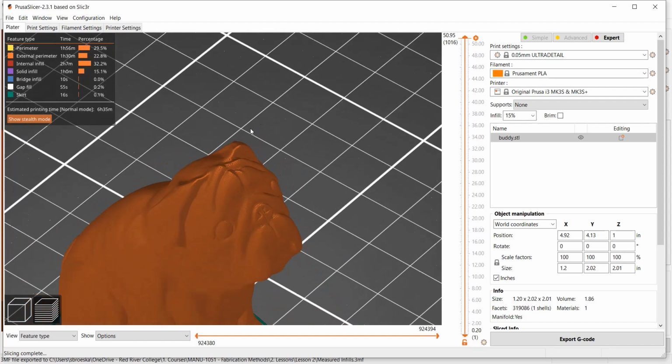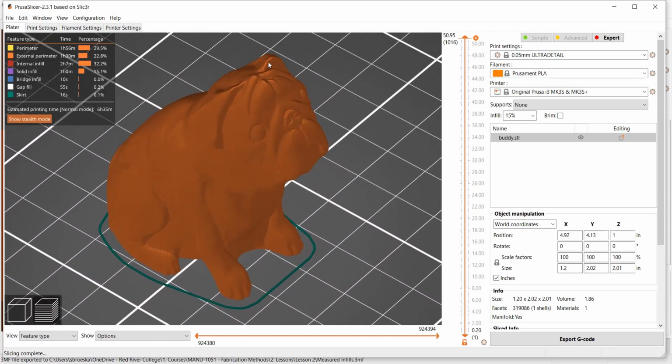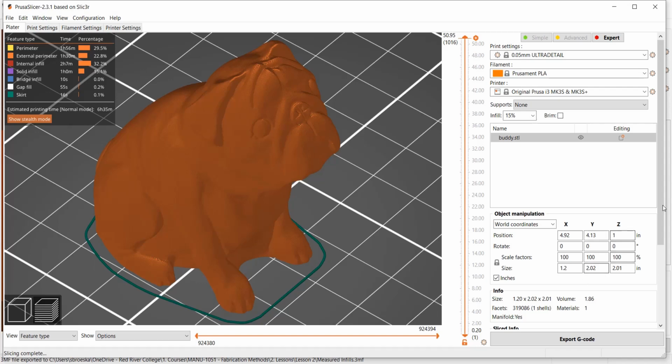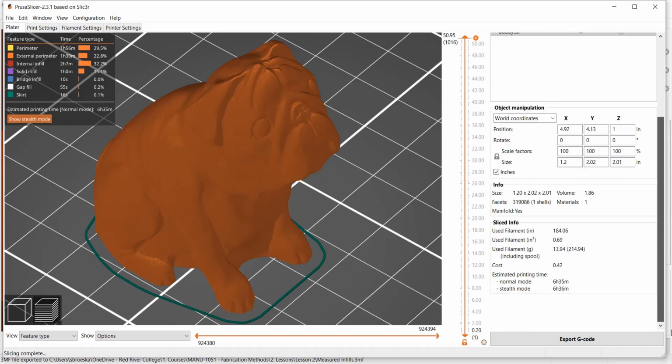But what are we sacrificing? That is the question. We're gaining quality, but we might be sacrificing something. And in this case, we are sacrificing time. So this takes 6.5 hours roughly to print versus our 1 hour print. So we could get 6 of these out at the coarse layer height as opposed to 1 at this really fine layer height, right? And it's using slightly less material, about 0.5 gram of material is saved in this method.